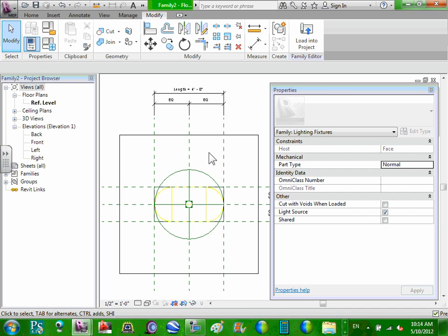The problem you'll find is if you tag the circuit, it only tags the primary connector. So you have to use text for those secondary connectors.